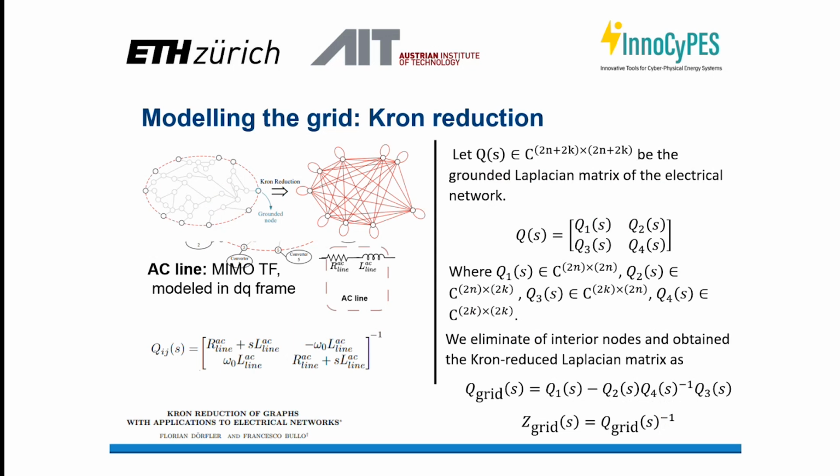So as I said, we have n nodes in the system, and active nodes that are the converters, and we're going to choose one node to be the ground node. In this case, the infinite bus. And basically we want to compute what are the equivalent links between every one of these nodes and the other converters in the grid. So we obtain something like this grid in here.